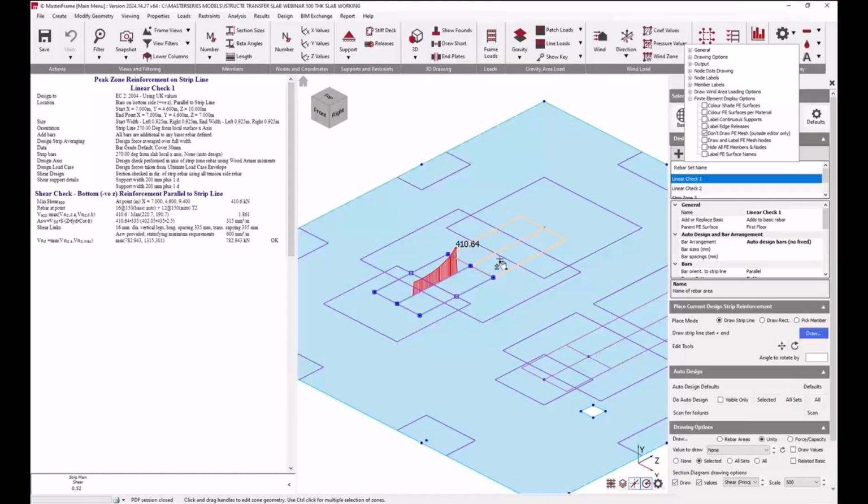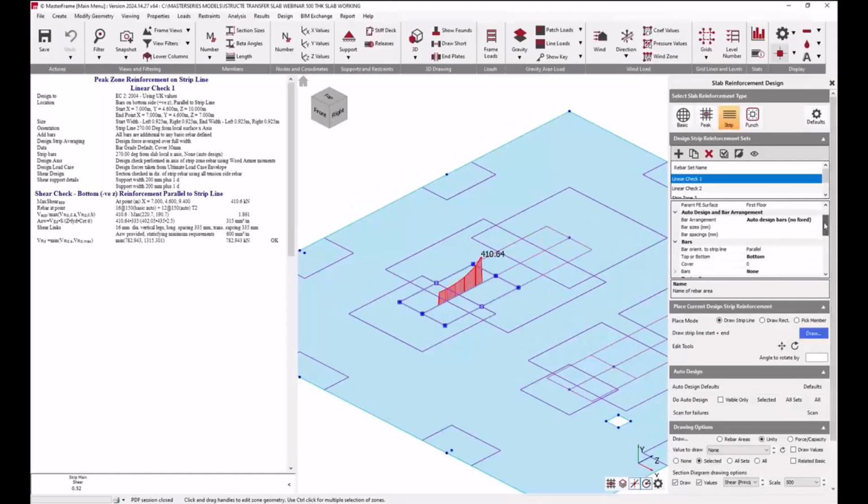One of the new things actually we have, and this partly answers this question here with regards to the new shear checks that have been added to the strip zones. Strip zones previously were only a means by which to add additional one-directional reinforcement bars to one side of the slab, either the top side or the bottom side. Now, you can use these strips without necessarily associating additional bars with the strip. You can provide the strip as is on top of the basic rebar without any additional bars, and it has the advantage of strip averaging the results to do the design, and the design will be done for the main reinforcement if appropriate using some strip averaged results, whereas the design for the basic panel reinforcement is done on a point-by-point basis. So where you have stress concentration, strips can be useful in a similar way to the peaks work, except peak zones provide reinforcement in two directions instead of just one direction. So a strip is a special situation of a peak, except it only works in one direction.